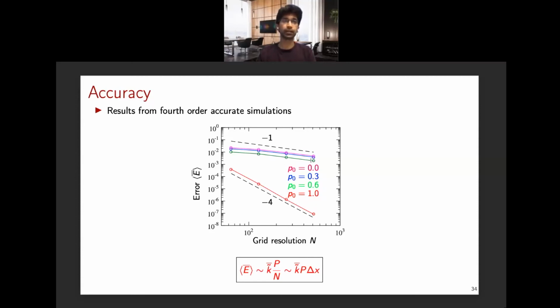You see that there are several orders of magnitude increase in the error when you do these things asynchronously. So now the question we want to ask is, can we deal with these low order accurate schemes and perform something like a DNS? Obviously, the answer is no. When you incur these huge errors with all these spurious oscillations, you will not be able to perform accurate simulation.